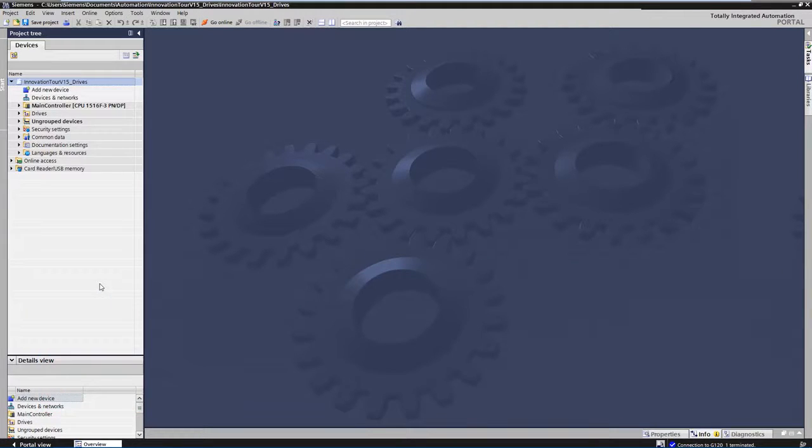In this video, we want to show you how easy and fast the Safety Integrated function of SINAMICS can be approved. Why do you need acceptance tests? The EG Machinery Directive and DIN EN ISO 13849-1 require the testing of safety relevant functions and machine parts after commissioning as part of the so-called acceptance test.